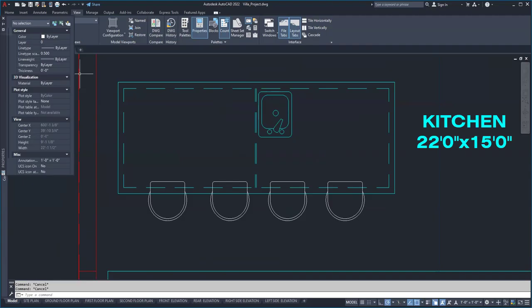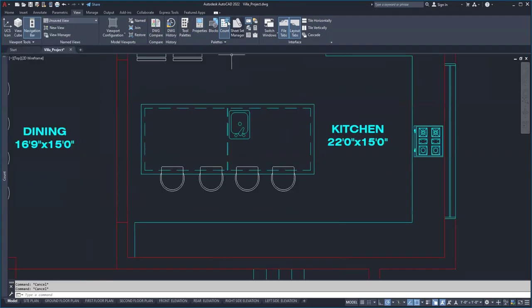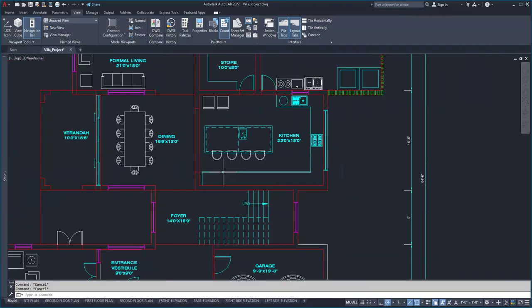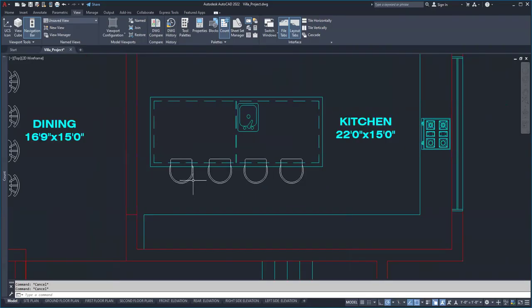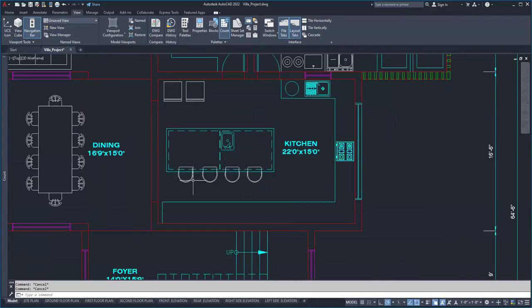So what was the main topic of this class? The main aim of this class was to teach you Count. Count is a function or command in AutoCAD which will help you count the number of blocks and also the location where they exist. It's kind of a helping hand where we can visualize which block is out of sync, let's say, synchronized. It was a small class. Actually, these are all topics for the ACP. I thought of just sharing some tricks and tips.